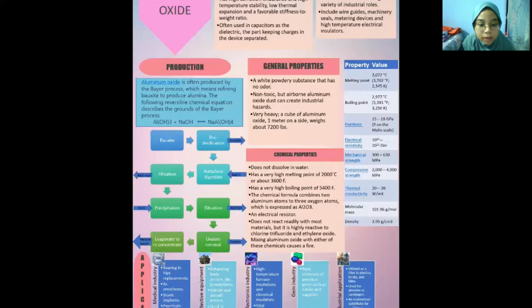All the aluminum hydroxide that settles at the bottom of the tanks is removed. Then, the remaining caustic soda is washed away from the aluminum hydroxide, which undergoes various levels of filtering. Finally, it is heated to completely remove excess water. After passing through a cooling stage, the fine white powder is produced.